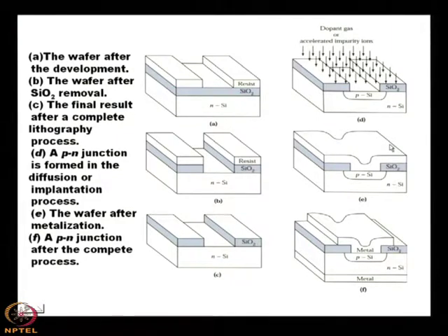Now, so far as the contact is concerned, generally the whole surface is given the metallization. It is done by thermal evaporation technique, we shall discuss separately, and what type of metal we choose, why aluminum is chosen for silicon, why if you use gold or platinum it will be a Schottky type of contact, why those things happen, that we shall discuss separately. Now, in our PN junction device, you know that on the principle of PN junction many devices are formed.